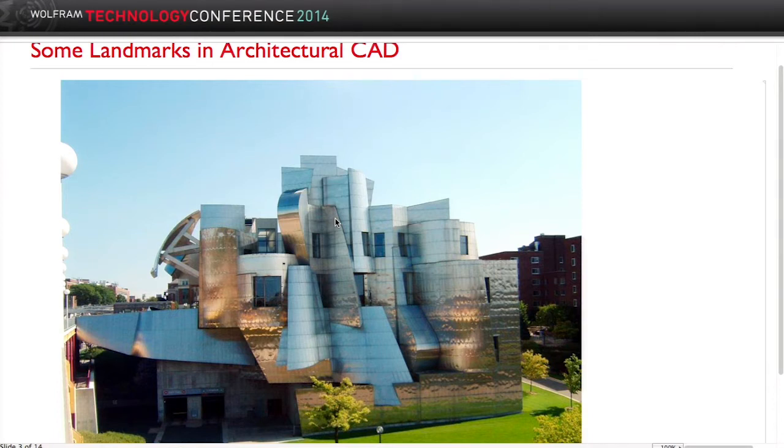So if you look closely, you can see some tip-offs that this wasn't designed by computer. For one, all of the surfaces are singly curved, which means you can take flat materials and easily clad the surface. The cladding itself is this very simple rectilinear grid, which simplifies things. And the surfaces you see are all actually very simple. They're planes. They're sections of cones and cylinders. So all this was done to make this geometry tractable.